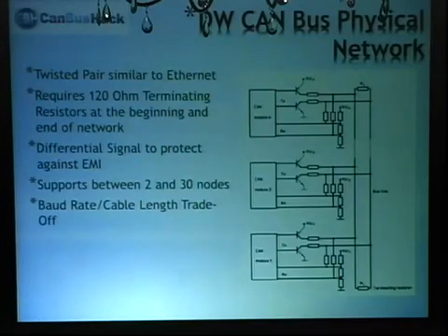So if you make a long string, this is the number one thing that I hear about from everybody who talks to me: I cooked it all up, it's perfect. I have my own CAN bus on my desk, and of course they didn't put the resistors there, and then nothing will work because you made it two antennas. Now they're just two big antennas if you don't put the resistors on there. So you got to put them there. Now you have a bus.